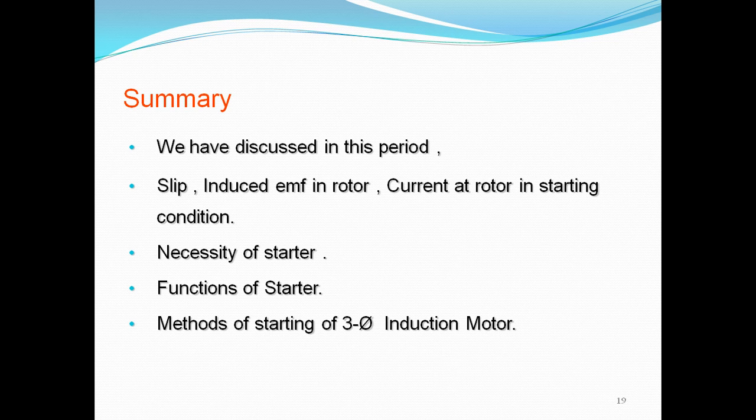So what is the necessity of the starter? The starter is necessary to reduce the high starting current. Why? Because at the time of starting the motor, the speed is 0. When motor speed is 0, slip is equal to 1.